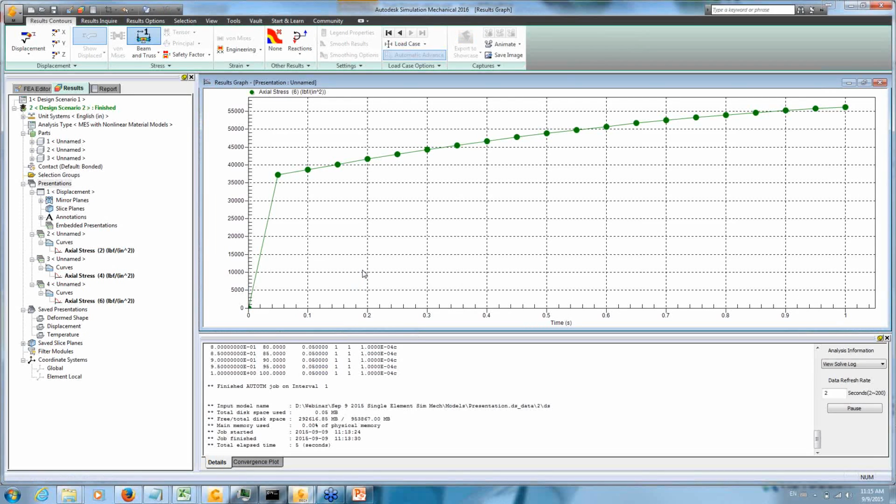And I think that's really good, Marwan, because it demonstrates one of the principles. If you're loading a structure beyond the yield point, you may be doing a linear material model, and if you're getting stresses that are higher than that, that's when you might want to switch to the nonlinear material model, correct?